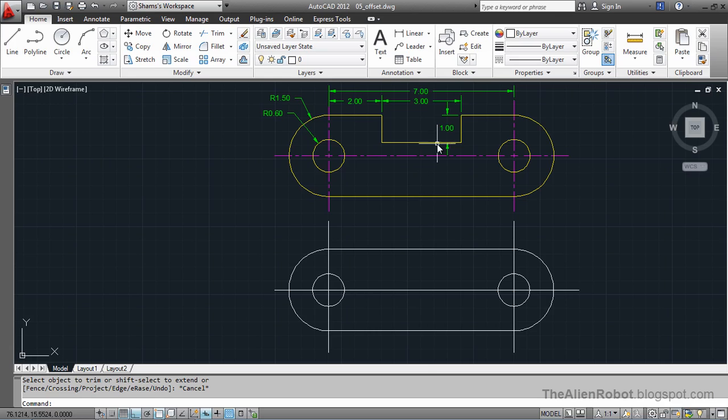Now let's first create these lower parts. Go to the offset command, then we'll give it 1 unit. Select this and escape, and press space bar, and we'll give it 2.2 units. Enter. Select this and copy it and escape, and space bar, give it 3 units, enter, select and offset and escape.